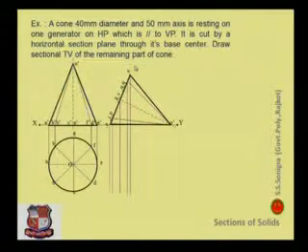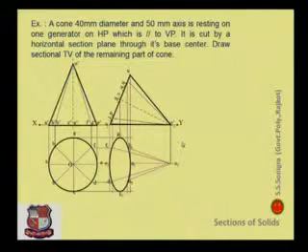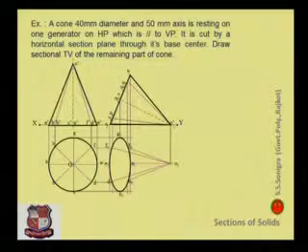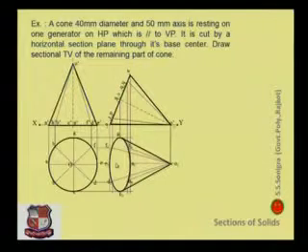dash and all these points which we exercised in the previous section on how to draw projections of solids. Draw vertical lines from all these points, horizontal lines from the top view, mark these points A dash, B dash, C dash, D dash, A1, B1, C1, D1, E1, F1, G1 and H1. Join them with a smooth curve, and from point O draw a vertical line, O dash vertical line, this is point O1. Join these points with a straight line, this is its top view. So this is just the projections of the given solid.